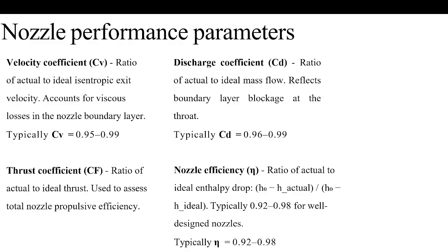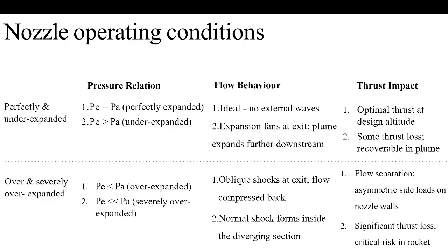This efficiency is theoretically noted as 0.92 to 0.98, but actual engines may not operate at these conditions. They will be a bit lower based on design considerations, back pressure, and losses, considering frictional losses, heat losses, all those things. So this would not operate exactly in this condition, but approximately similar to those cases. Okay, so moving further, these are some of the operating conditions of the nozzle.